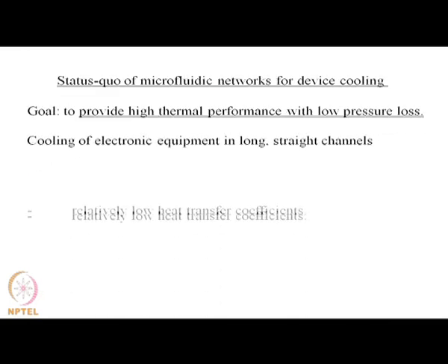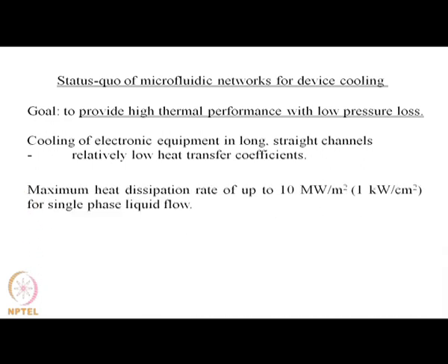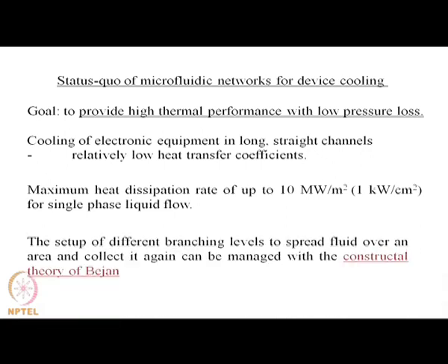So we are going to look at what's the status of microfluidic networks for device cooling. Now obviously what we would like to do is to provide high thermal performance with low pressure loss. So one such requirement is the cooling of electronic components, and mostly long straight channels are used. Now the long straight channels are relatively easy to fabricate, so there is no problem of distribution of liquid, but the problem is this has relatively low heat transfer coefficients.